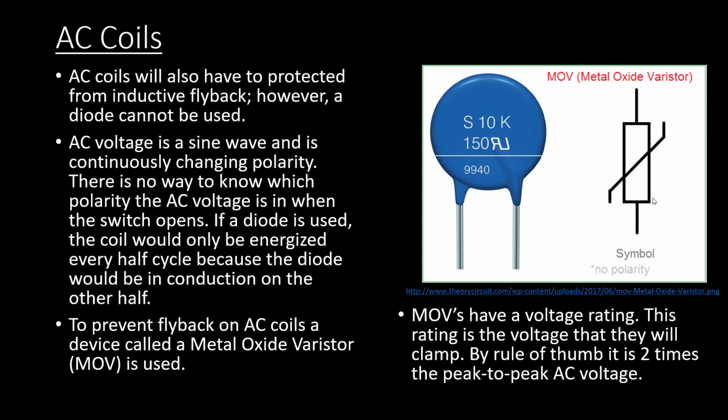So let's say 120 volts. I'm just going to guess at a number here. I think peak to peak is around 160 some volts, and really I'm just pulling that out of the air right now. If I double that, I get 320 volts. So I'll go out and I'll look for an MOV, and I may not find 320. They may have a 300 volt one or a 400 volt one. You know, either one of those will work.